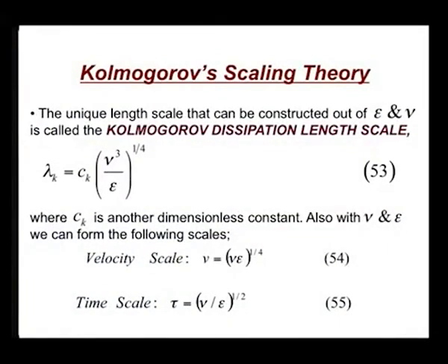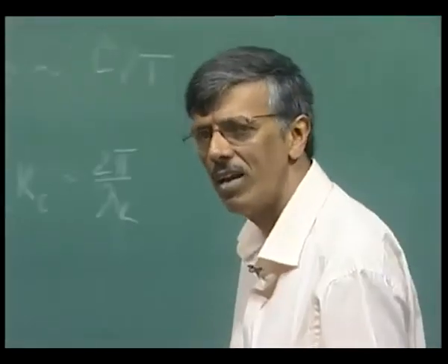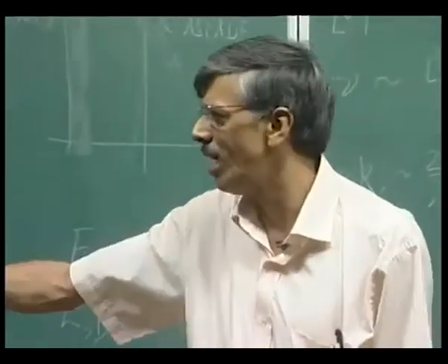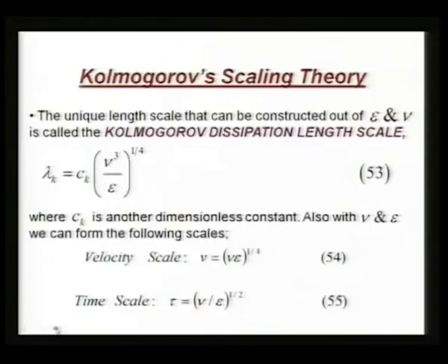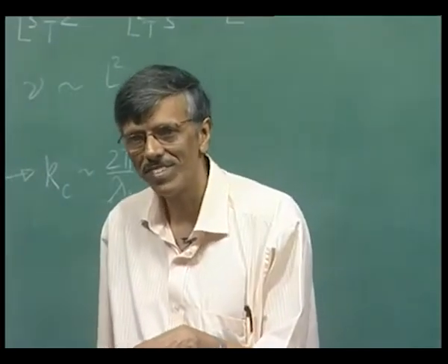That more or less defines everything, is it not, the way we have been non-dimensionalizing the Navier-Stokes equation. What we needed there was a velocity scale, a time scale and a length scale. So we have all 3 of them. What is interesting is that sometimes we have converted the velocity scale and length scale into a time scale, right. We can do that, but here we are talking about, let us say, these 3 things being independent.